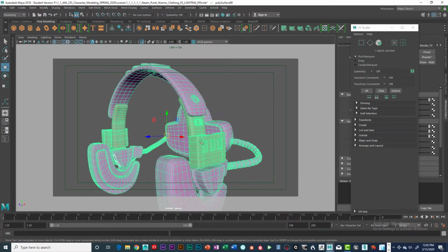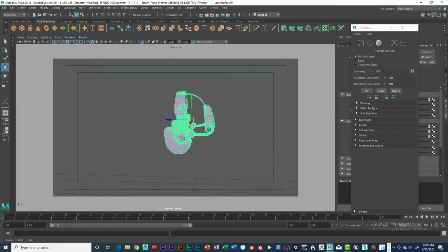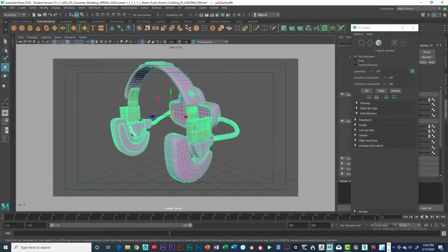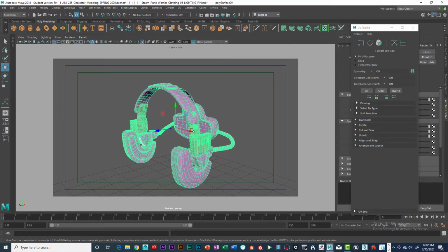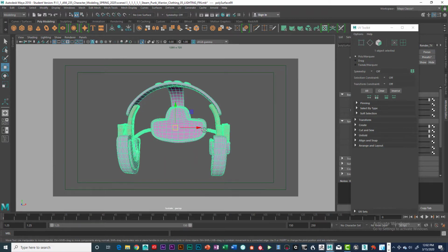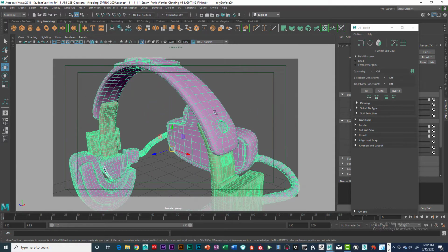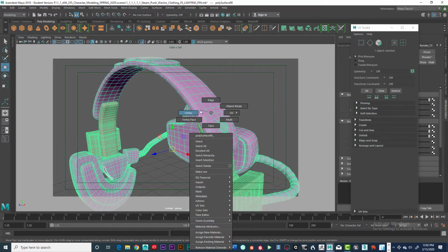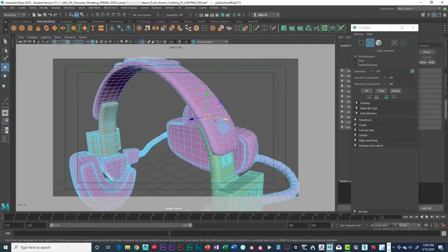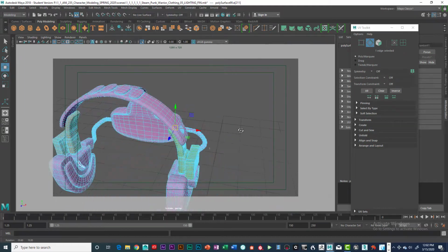If you get lost or something happens with this object and you can't twirl around it, basically if you select the object and hit the F key, it will focus on the center rotation of that object's pivot. What if that's not working? If you're working on something, you can just click on anything like an edge and hit the F key, and it will focus on that and rotate around that particular area.